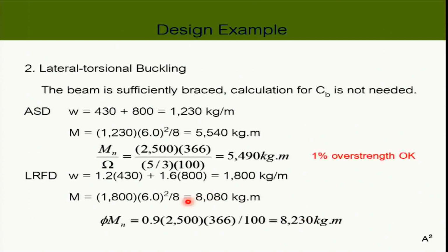So in terms of LRFD, it's safe. Because when you compare the live load over dead load ratio, it's less than 3, right? It's less than 3. So it gives pretty much a similar number. So for LRFD, it's perfectly safe. For ASD, it's a bit overstrength, but that should be okay.